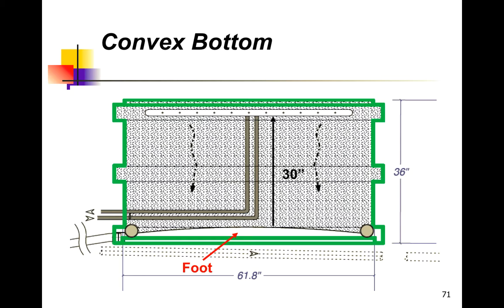So to install the low flow basin, when we're done, the basin will look like it does here, where we have a convex shape to the bottom of the basin. We're going to have a 3-inch ADS pipe that's going to run around the inside circumference of the basin. Our supply and flush line will come in near the bottom and then go vertical up through the center. It'll be filled with media with our low flow coil on top, and then it'll also be covered with media.